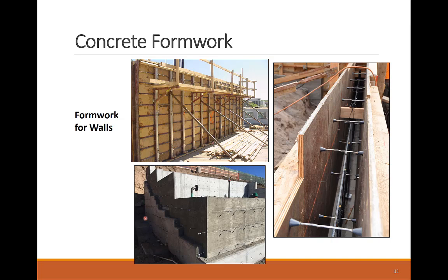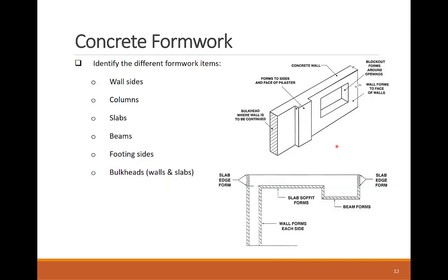In large structures, the formwork panels are held laterally by using cross ties that are embedded into the formwork and removed later with the form, leaving behind the tube holes that need to be filled, as we'll cover in dry finish treatment work.